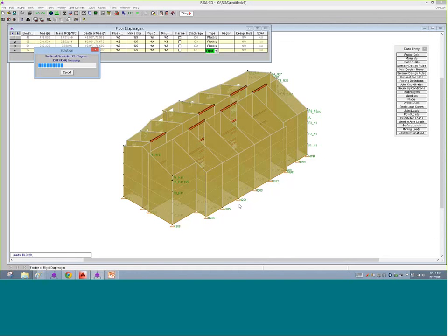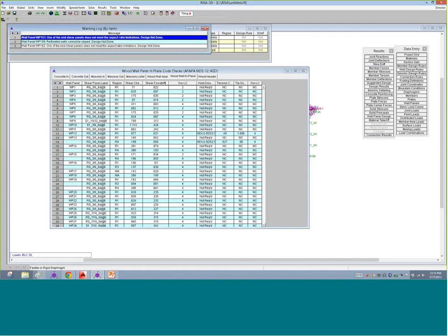But also, you can have cases where buildings will have rigid diaphragms on certain levels and not on others. For example, maybe you can assume rigid all the way up the structure until you get to the very top and your roof is flexible. That might be a common case too.